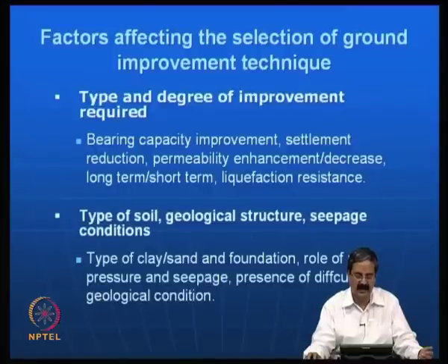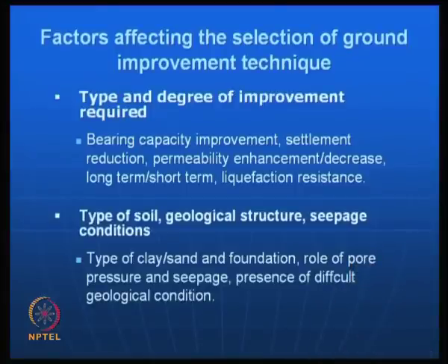And seepage also. If there is a lot of seepage, what happens? The soil particles come out. So, that is another problem. Then the presence of difficult geological conditions, as I mentioned a few minutes back, like karst deposits, which have a tendency to form holes, is another risky thing. So, the type of soil, geological structure and seepage conditions influence the ground improvement technique choice.